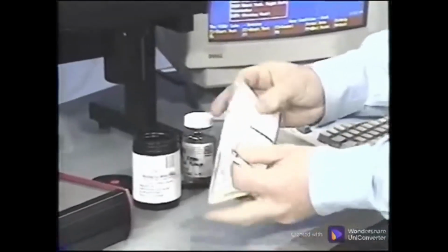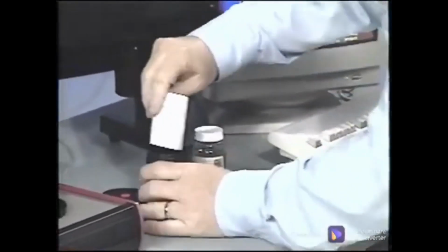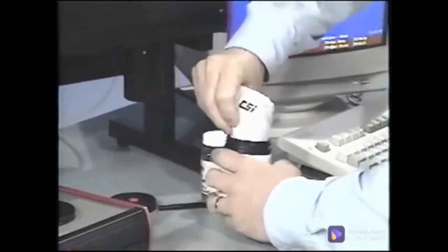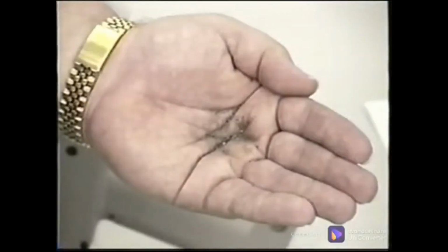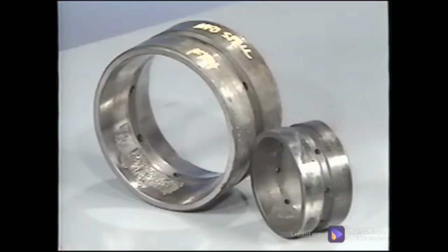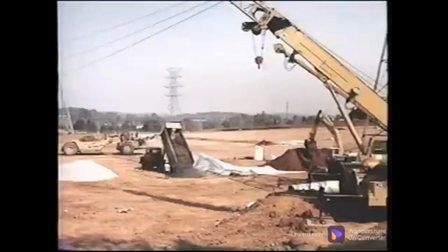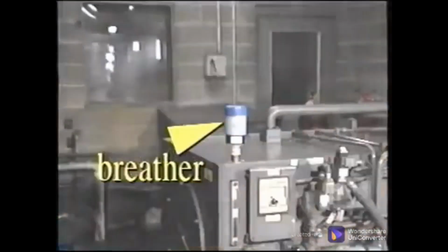When a sample is abnormal, then send it to an off-site lab to analyze the particle type and determine whether it is a contaminant or actually a wear metal. The most common contaminant is silica, which is sand or dirt, and its crystalline structure is much harder than machinery components, even carbon steel. It is 3 times harder than the case-hardened surface of the races of a rolling element bearing. Since 2/3 of the Earth's crust is covered with silica, it is a very likely contaminant which can enter the system through the breather of the oil sump. When silica is present, wear particles are usually present also.